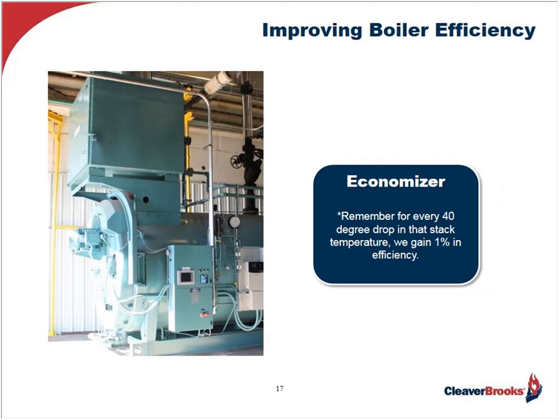Finishing the major burner observations, we move on to other areas and external devices which can save energy. A big one, as I showed you in the beginning, is the stack loss. Now, if the boiler is over 150 horsepower and it's operating over 100 pounds pressure, it may be a candidate for a stack economizer for recouping some of the stack loss energy by putting it into the boiler's feed water, which is coming from the feed water tank, which in most cases will be a deaerator, but it could be an open vented receiver.